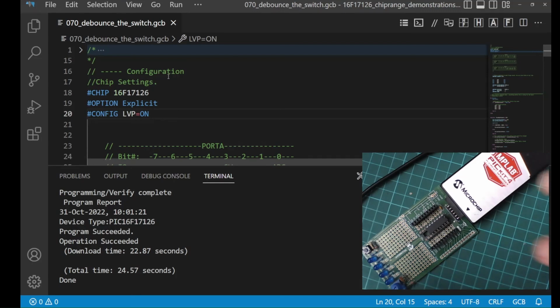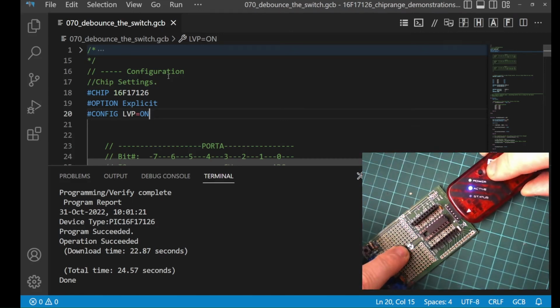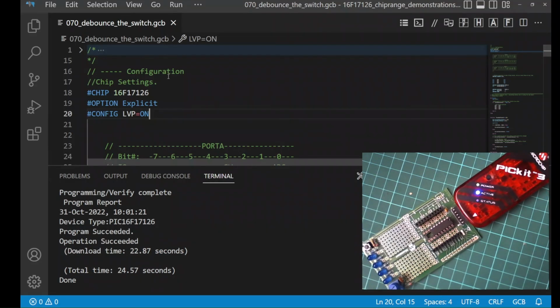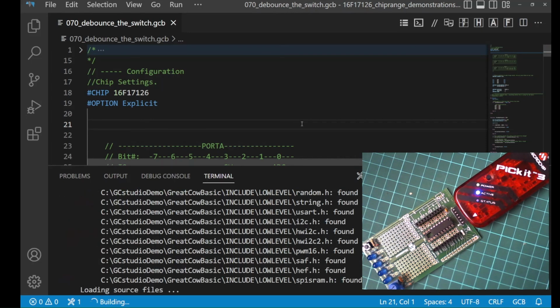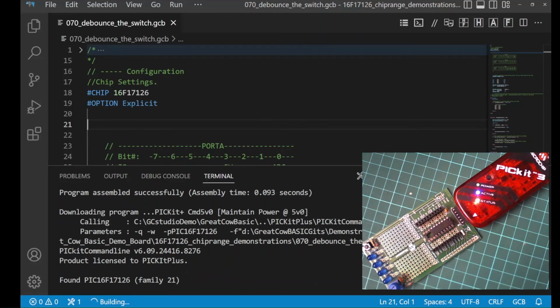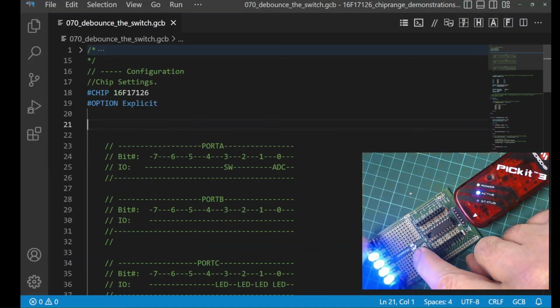So I'm just going to return back to my original chip. Is that what I have here? Yeah, back to my original. Stabilize the cable. I can leave that there if I wanted to. Back to programmer preferences. Just remove by dragging down the entry, and I'm now back to my quicker programmer. Close that, push that button, and we're operational. Great.